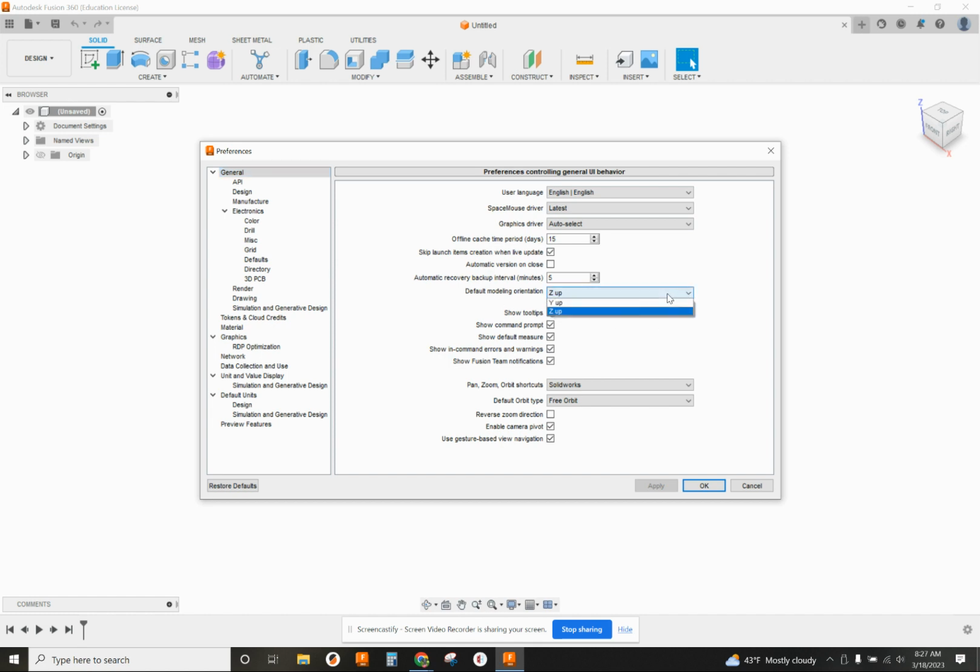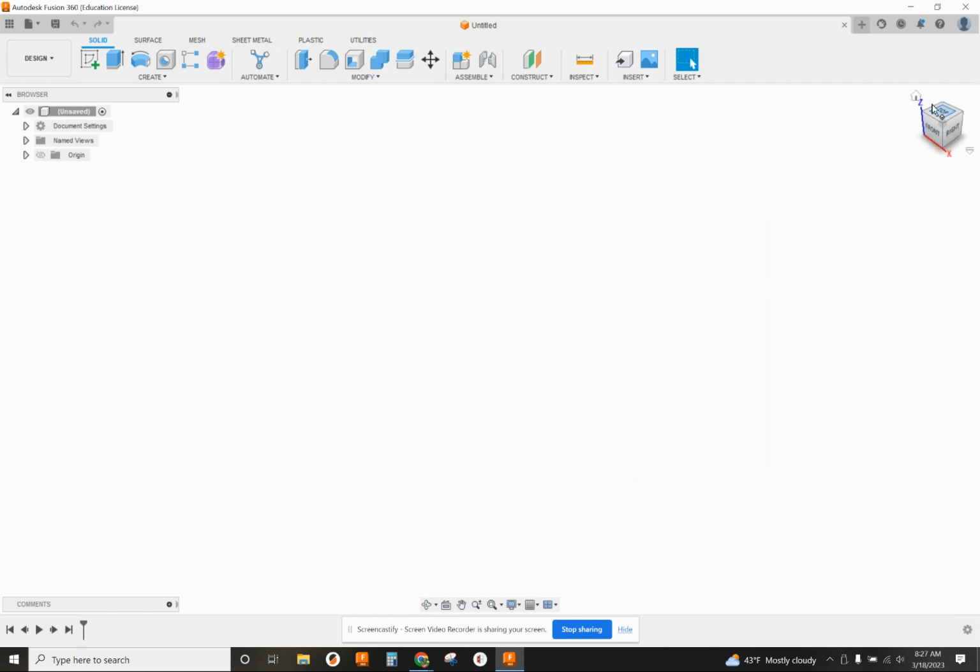I want to change that. So I'm going to click on this, drop down, and click on Y up. And then Apply, and then OK. Now, nothing changes, as you can see up here, yet. So what we're going to do is just X out of this tab that we're in. So it says Untitled. And it will pop up with a new one, and now it's oriented correctly. You can see Z facing towards us, Y is facing up, and X is facing to the right. That's the correct model orientation that we're going to need to use for our design space.